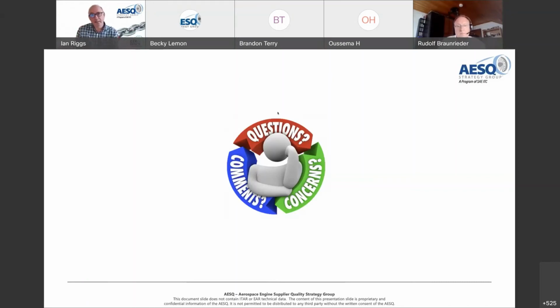The reality is, when you first put your FMEA together, a lot of those potential causes will be quite hard to determine how often they actually happen. Therefore, on a first pass of the FMEA, what we've said in 13004 is use the score you would get from the failure mode, and you can use that for all of your potential causes.